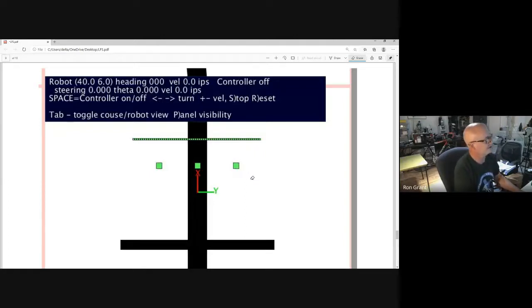This sensor would give our program a 1.0 reading, whereas this sensor here in the center would give our program a 0 reading. And if the sensor was located part on the line and part off, we'd have some value between 0 and 1. So the larger the area we're sampling, the more opportunity to see a piece of the line.